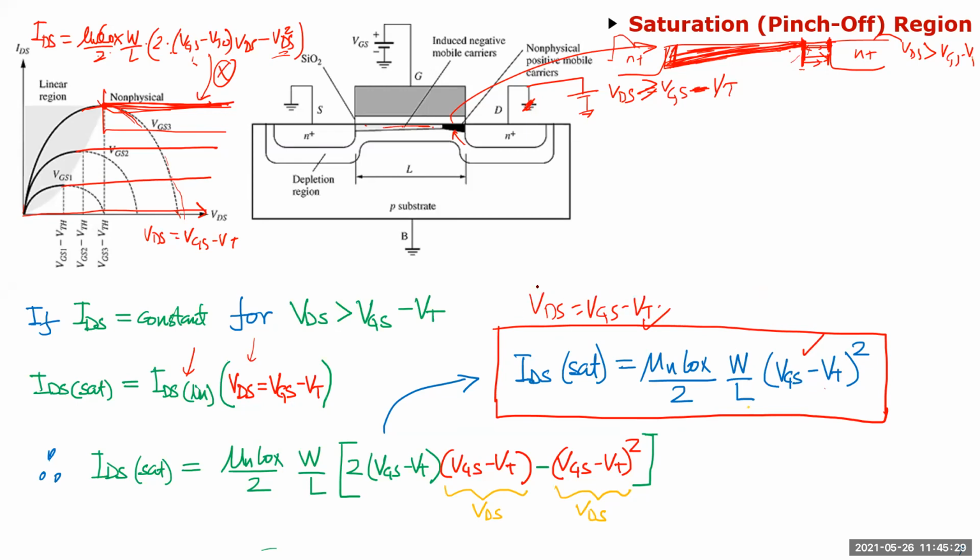Okay. And this is very important in analog or digital design. We call this VGS minus VT by a lot of terms. We call it Von, we call it VDsat, we call it Vexcess. There are different names, but they all mean this excess voltage over here. So essentially, in all the texts you'll see two regions of operation. One is the linear operation and one is saturation, what you saw. But I showed you that you can take the linear region and even approximate it for smaller VDS and show that it is really linear for small VDS.